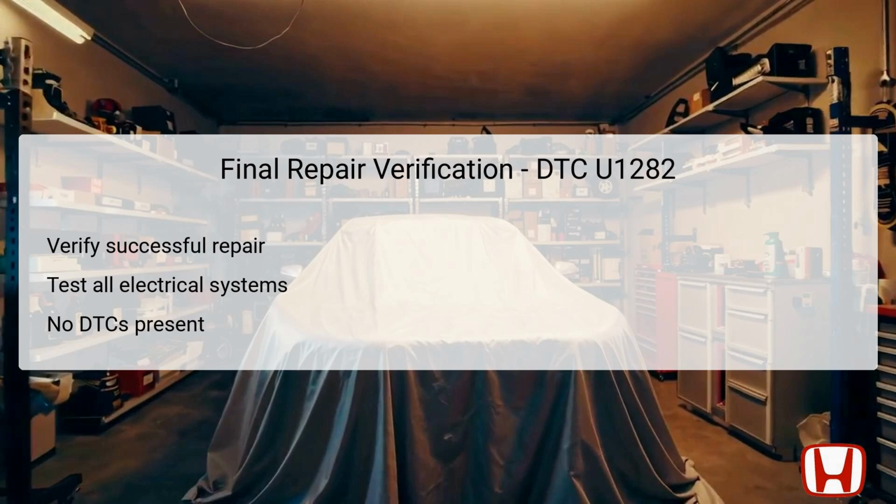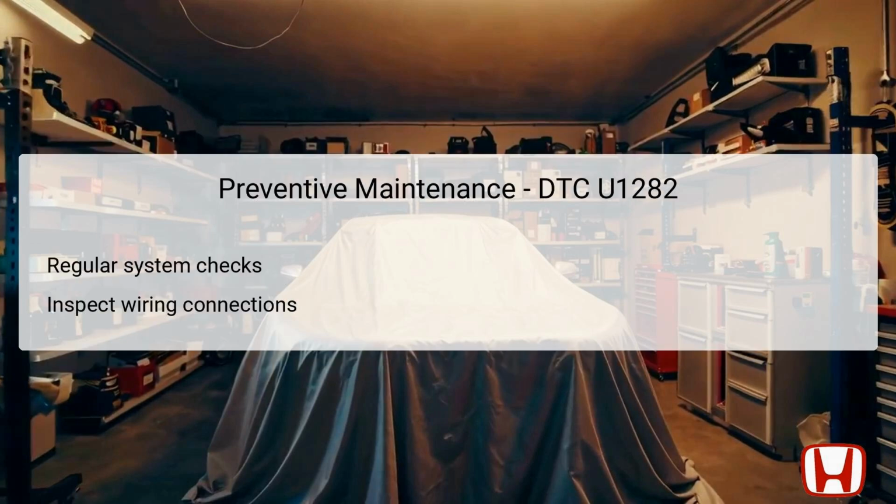After the tests, performing another scan with the HDS can help ensure that no DTCs are currently present. If all systems are operational and no DTCs reappear, then the repair can be deemed successful. This verification step is crucial, not just for confirming repairs, but also for ensuring the safety and reliability of the vehicle moving forward. Preventive maintenance is essential for avoiding future occurrences of DTC U1282 and ensuring the longevity of the